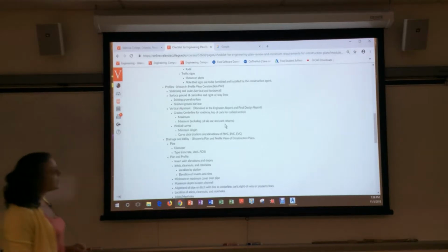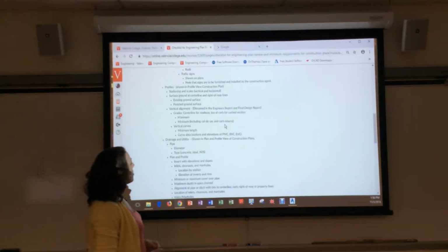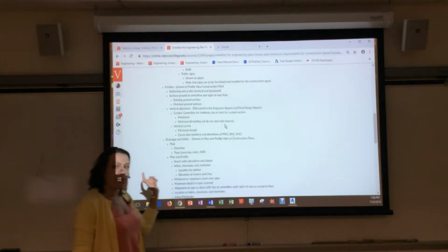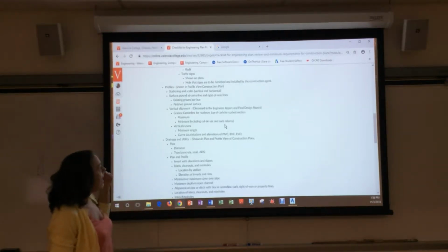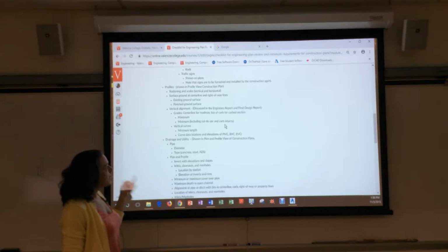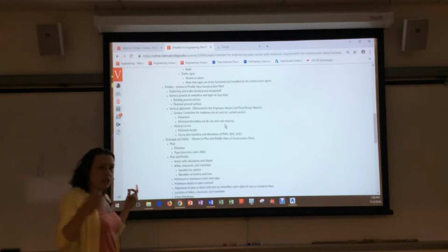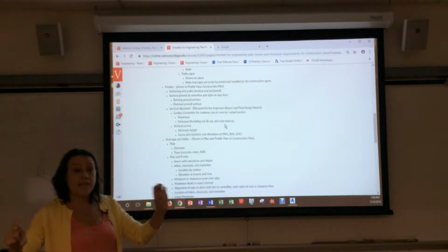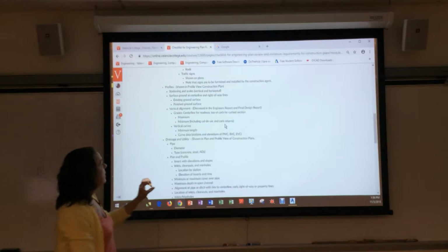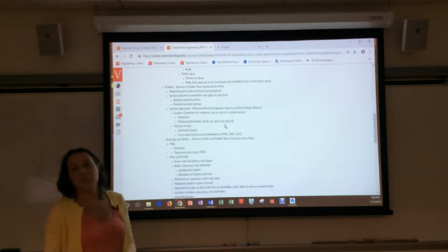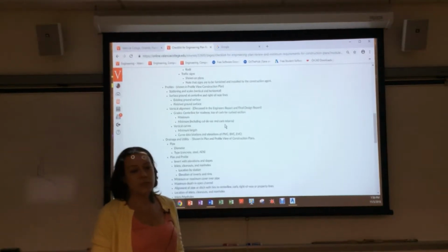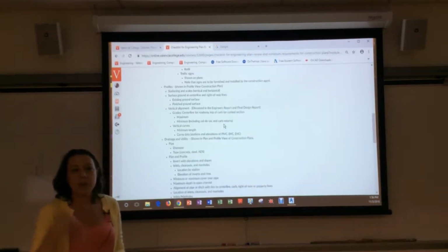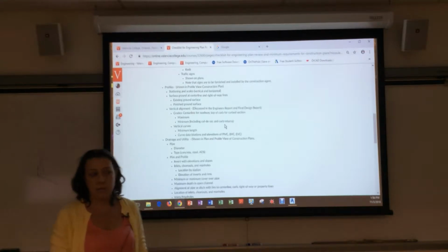So in profiles, the stationing, the scale, surface, the existing ground is going to be a dashed line. The proposed ground is going to be a solid line. You have vertical alignments. You'll have center line of the roadway. Every stationing at the bottom of your band should be every 50 feet. It should have an existing grade and a proposed grade. Now, the more information you have on your plan, the easier it is for the contractor to build. If you don't put enough information, he's going to be calling you up to get clarification.